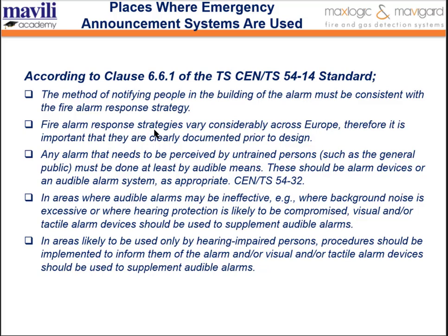Fire alarm response strategies vary considerably across Europe, and therefore it is important that they are clearly documented prior to design. Any alarm that needs to be perceived by untrained persons, such as the general public, must be done at least by audible means. These should be alarm devices or an audible alarm system as appropriate with these standards.